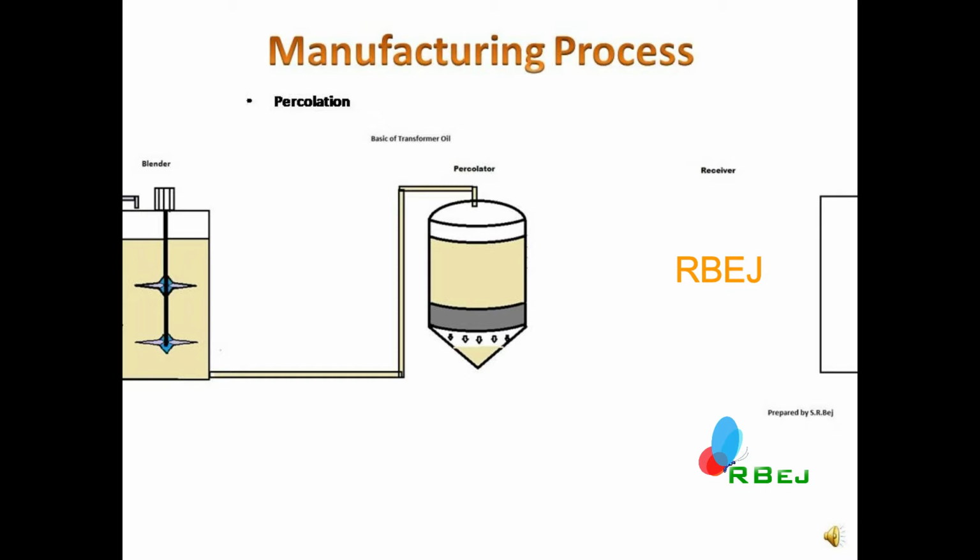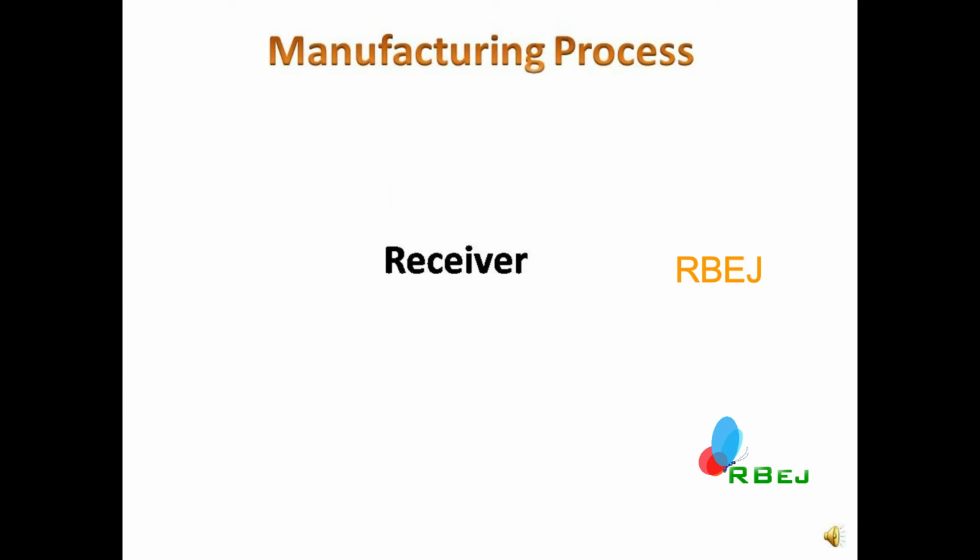A perforated plate or a wire screen at a slight distance above the bottom is provided, over which a heavy canvas blanket is placed and clamped to hold the clay in the filter yet allow oil to pass through and out of the filter. Size of these filters varies considerably, from small capacities to several hundred.